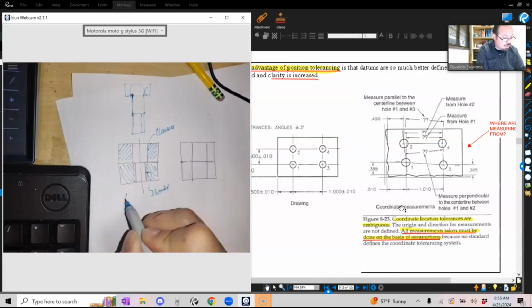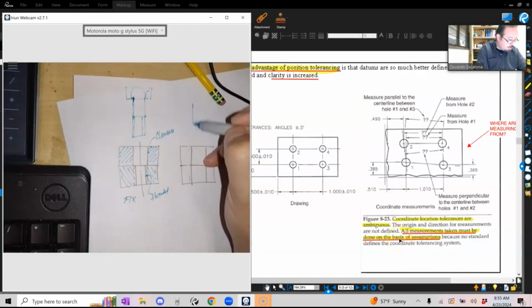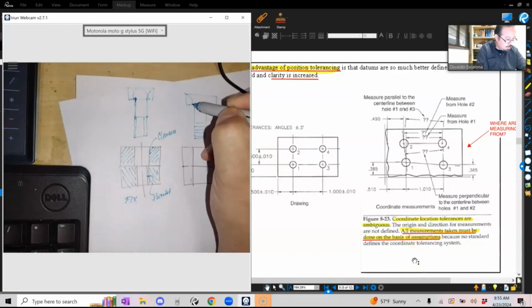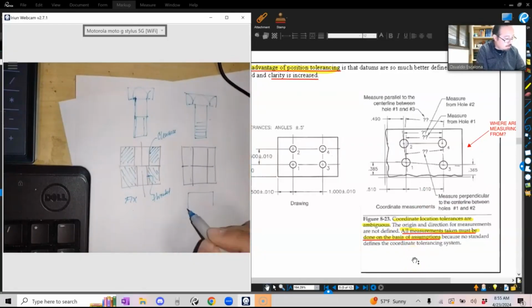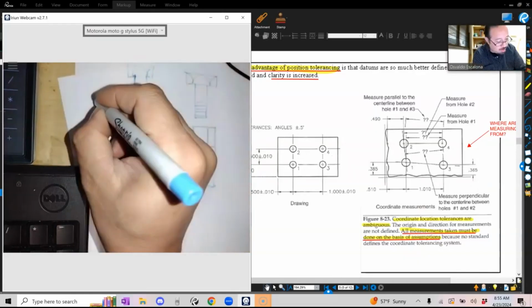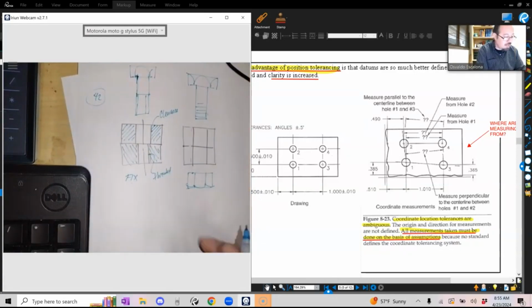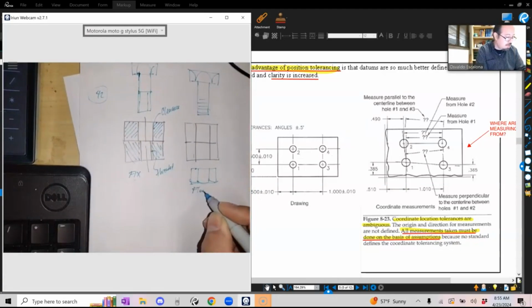We call this fixed fastener condition. In the other one, in order to bolt, I'll have clearance holes in both parts, and here I'm going to have a nut. The bolt goes all the way through both of the parts. This one is floating, because my bolt floats with these two parts.